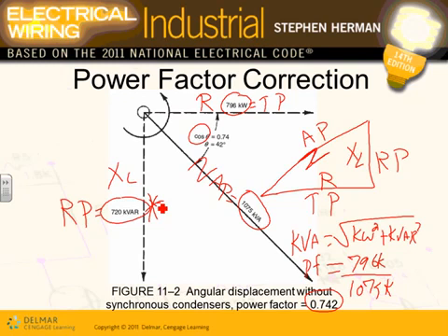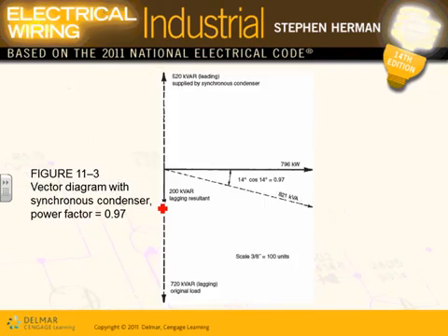So in order to neutralize the inductive kVAR from the coil, you add capacitive kVAR. How do we correct power factor? By adding capacitors. I have an inductive kVAR of 720 kVAR. If I want to get rid of it, Adam, I just add a capacitive kVAR of 720 to neutralize it. Any comments, guys? Any questions? You'll see this one in a second.